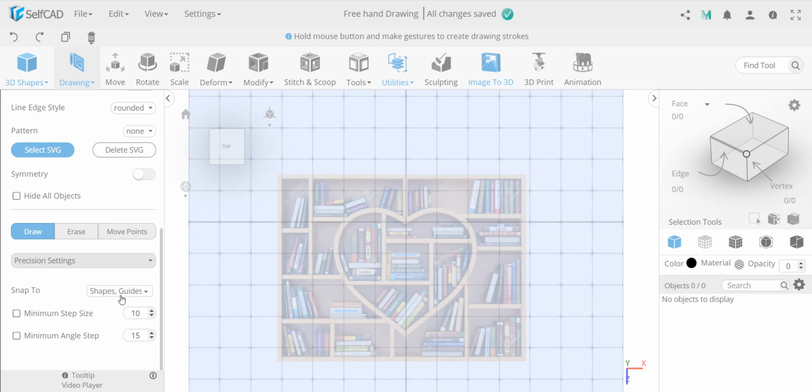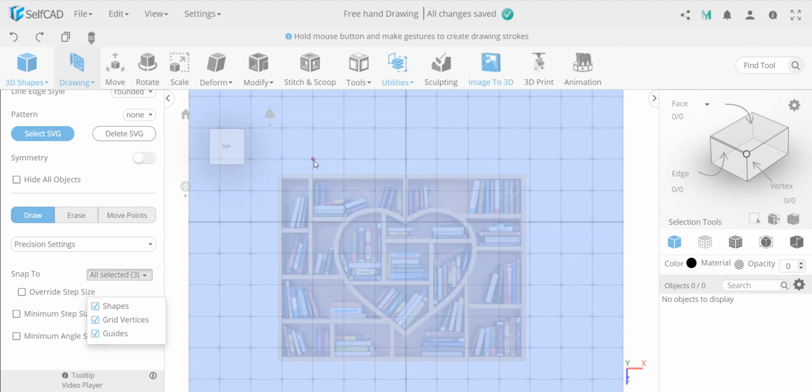There are a few ways to do that. One way is I can snap to something. I can turn on snap to grid. So for example, you can see it snaps to, it's called grid, but it's actually not the grid, it's the vertices between the boxes in the grid. And I said, I think in the first video, that you'll see later when it comes to drawing why sizing the grid is important. This is one of the main use cases where you need it: if you want to model something, not really tracing something, or just in general, and you want to have measurements based on different things, you can create your grid based on the sizes that you're going to use, and then keep on snapping from point to point, which makes it very, very helpful in different types of drawings.